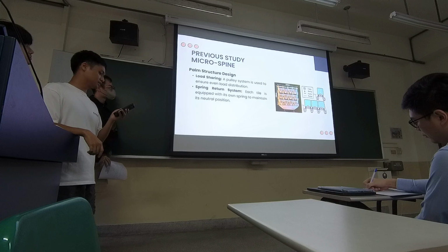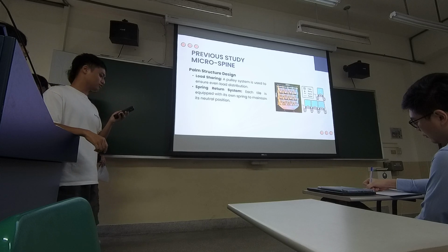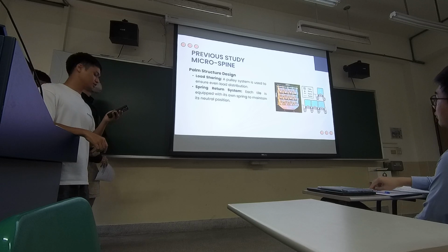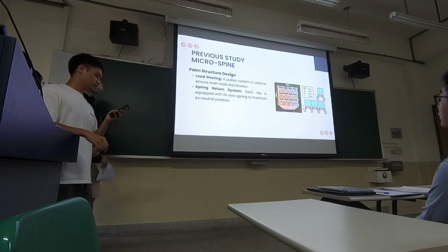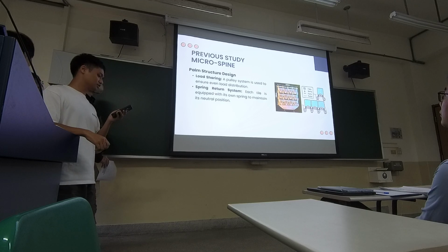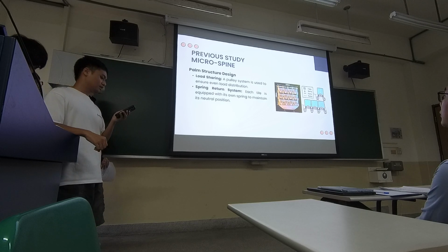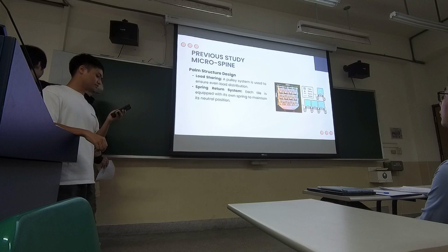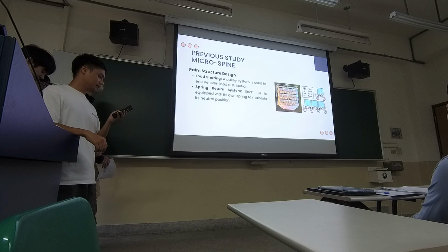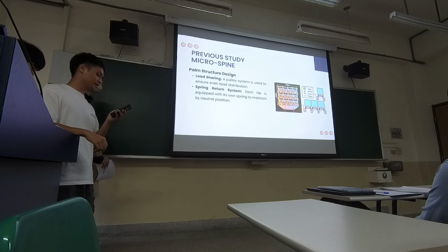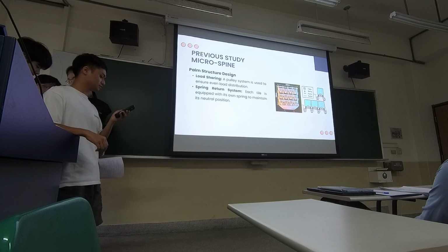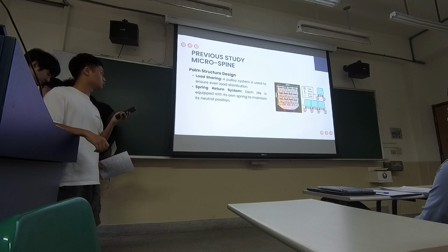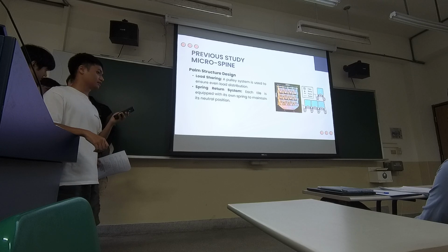And the design of the pad is optimized for climbing. A key feature is the load sharing system achieved through a pulley mechanism, ensuring the load is evenly distributed across all tails. This allows the robot to grip surfaces more securely, even on uneven terrain. Each tail also has its own spring mechanism, which returns the tail to a natural position when not engaged, keeping the pad ready for the next grip.